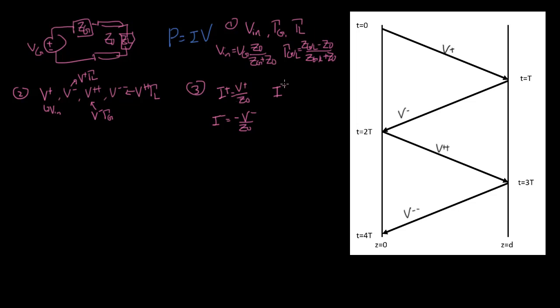And then the reflected wave off of that is going to be, again, positive. So this V plus plus that you found over here, divided by Z0, and then I minus minus is, again, don't forget the negative sign, or I will cry when I see it. That's right. Divided by Z0.